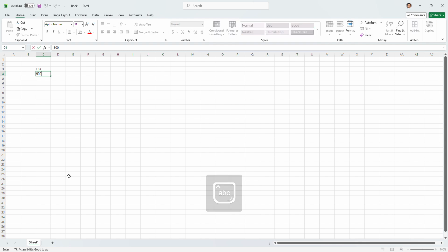All right, so our design parameters: we're going to use 9,000, 8,000, maybe 7,000 psi concrete strength for the wall. This is f'c and this is in psi, right? Now, what is the Young's modulus? I usually need ksi. So for typical normal weight concrete, I can use the formula for Young's modulus, 57 square root of f'c, with 9,000. So okay, 57 times square root f'c, that's our Young's modulus for 9,000 psi concrete.